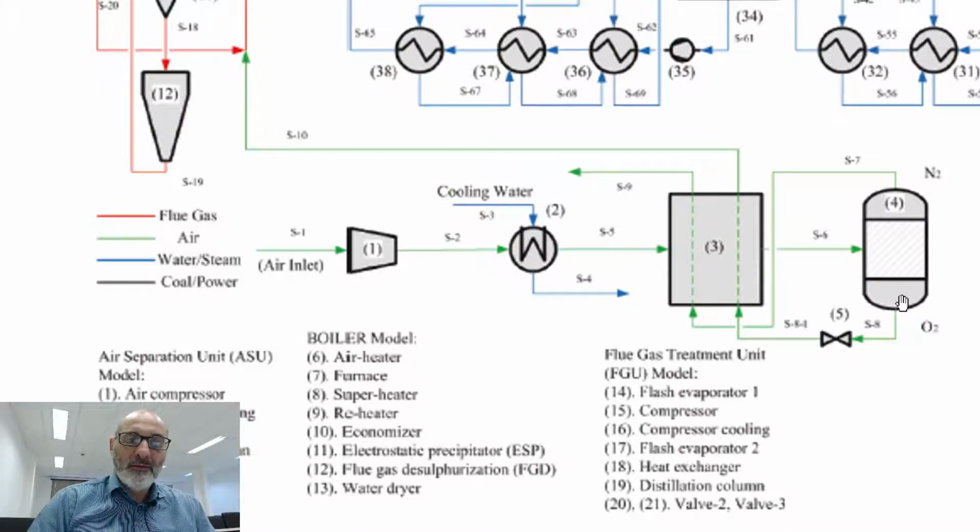But before here you have liquid oxygen. Okay, liquid oxygen at high pressure because you compressed here. If you expand liquid oxygen, its temperature is going to drop dramatically, minus 160 degrees or something like this. It depends on the pressure. And these cold gases can be used to cool, because when you compress air, it gets hot, so you avoid spending energy, for instance, in this refrigeration process here.